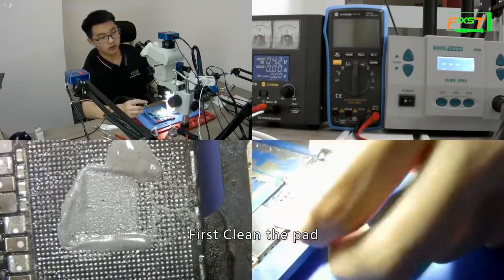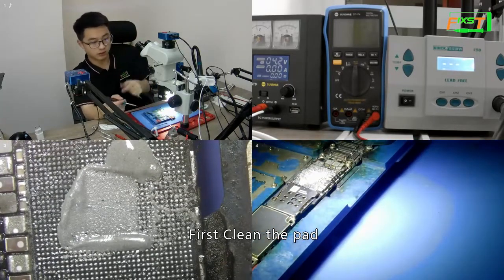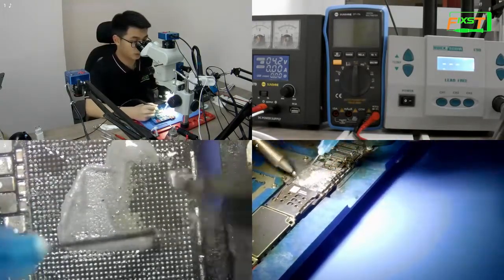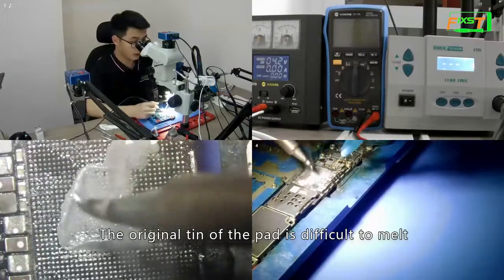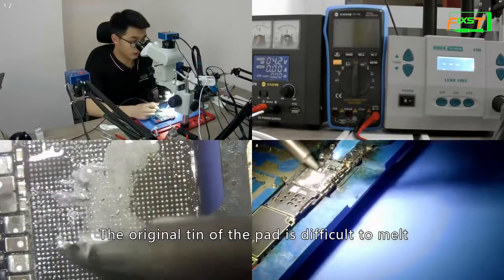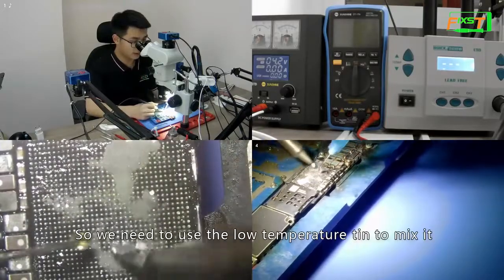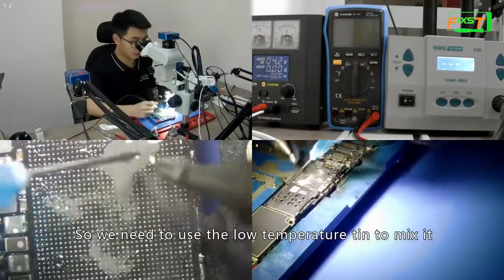First, clean the pad. The original tin of the pad is difficult to melt, so we need to use low temperature tin to mix it.